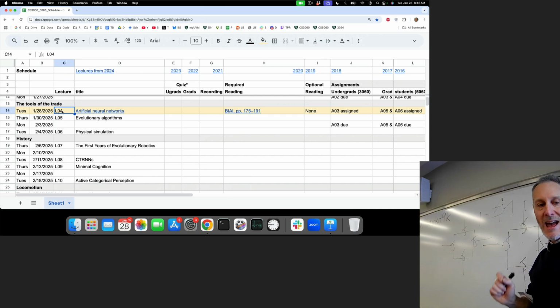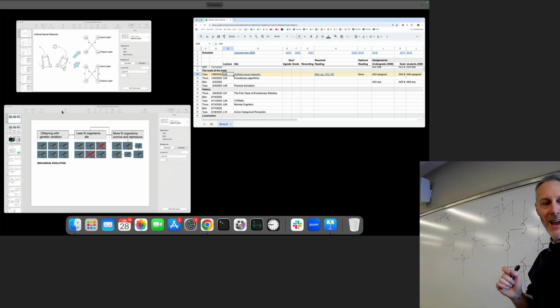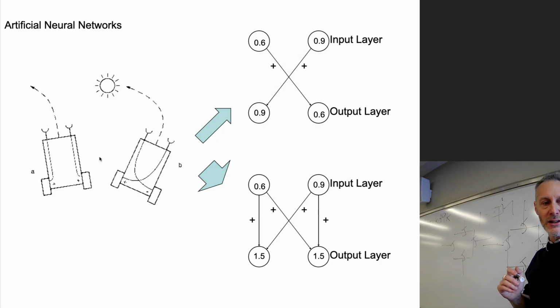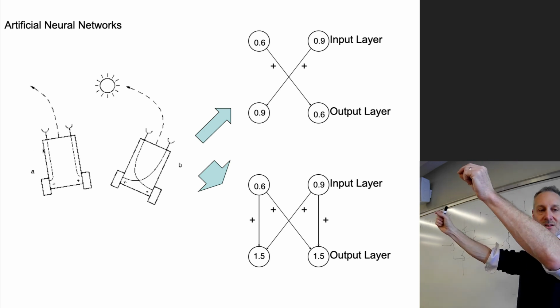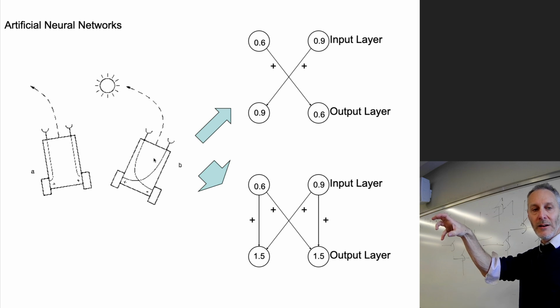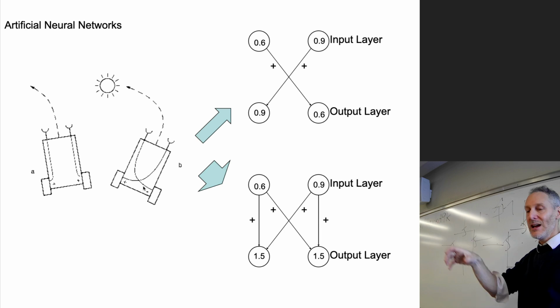We're going to look at everything that underpins robotics and modern machine learning and deep learning today, starting from the beginning. Actually starting from Braitenberg vehicles. Hopefully, Braitenberg vehicles are intuitive to you now, familiar territory. We've got a robot made up of 2 sensors, 2 motors. We can connect those 2 sensors to those 2 motors either ipsilaterally or contralaterally. And if we then take this little neural network made up of 2 connections at the front, 2 connections at the back, and 2 wires, if we drop that into a robot, we get behavior.